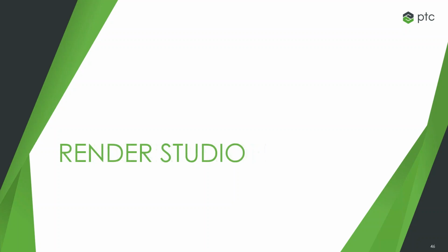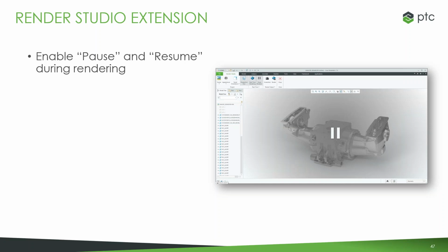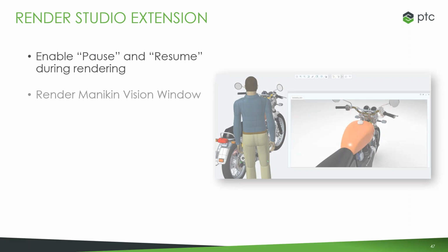7. So a couple of other applications I want to touch on before we begin to wrap up for the day. So the first thing is around our Render Studio. So there's a few new options in here as well. The first thing is the ability to pause and resume during the rendering. So normally when you're in this mode, it's kind of constantly running by default. But now if you know that you're going to go through and make a couple of changes, you can simply pause that render and give your computer a break while you're going through and making changes.